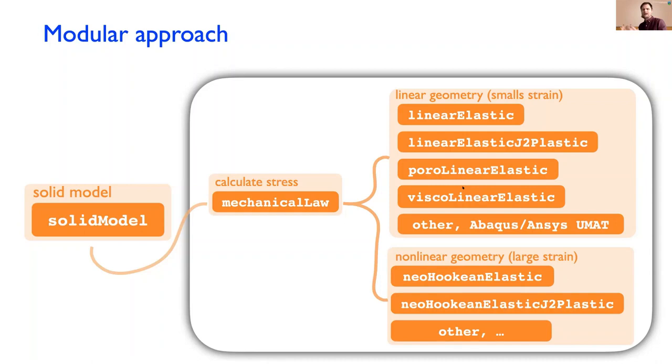Let's say if you're at the macro scale, if you just want to capture the principal directions of your laminates without caring about the plies, then that's probably fine with some of the available tools. If you really want to specify the individual plies and their directions, I know, for example, Abaqus has a composite layup tool that lets you define all of that and calculates the equivalent properties. That's not available here, but in theory, you could implement it if you really wanted it.